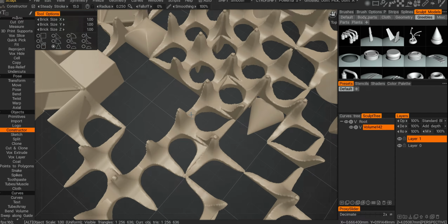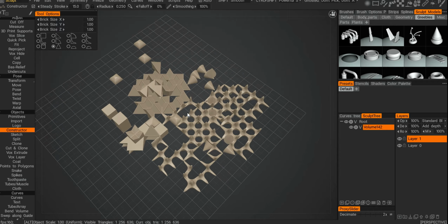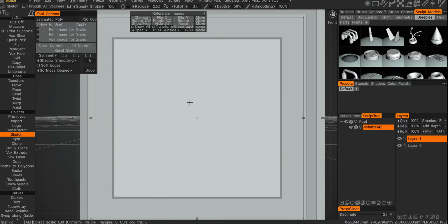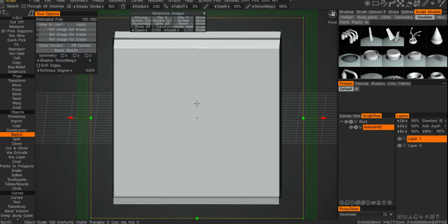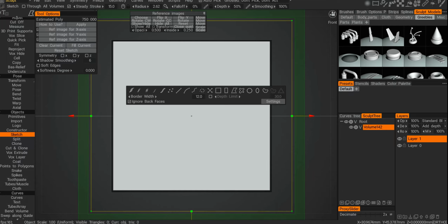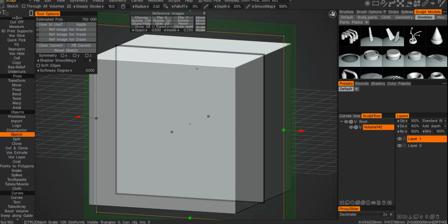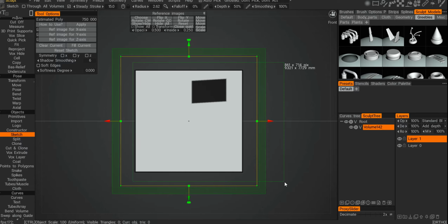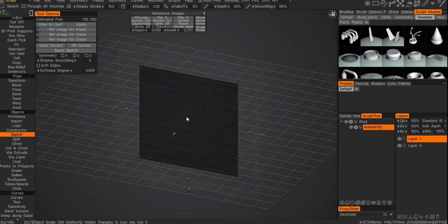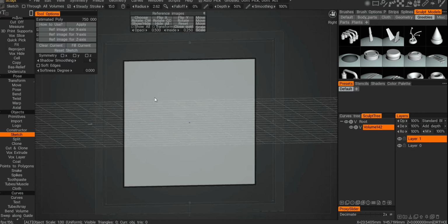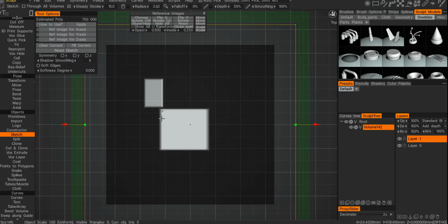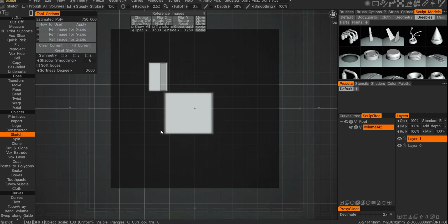And that's basically what it does. Sketch tool is quite a powerful tool. So first of all, I have to exit the perspective mode, go into the orthographic one, and then press E and start to paint. What I can do is if I press Control, I can remove all those fillers. I'll keep that one, and then I can start to unfill. And this is where we can use triplanar projection to build shapes.